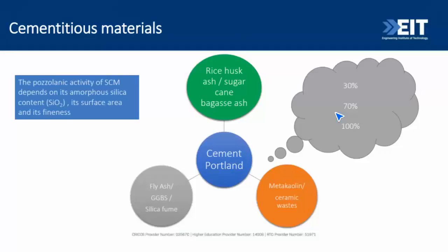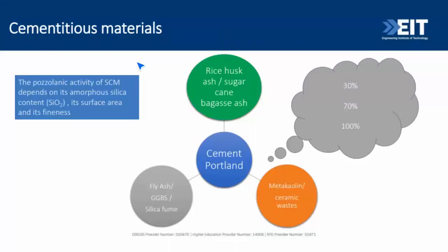So these are some results we have from the literature. The main target is to identify, regarding this type of materials, the ones showing a significant content of silicon dioxide, because this is fundamental to obtain pozzolanic activity. So we also call them supplementary cementitious materials. We have blended cement available in the market nowadays. It's a very important point.